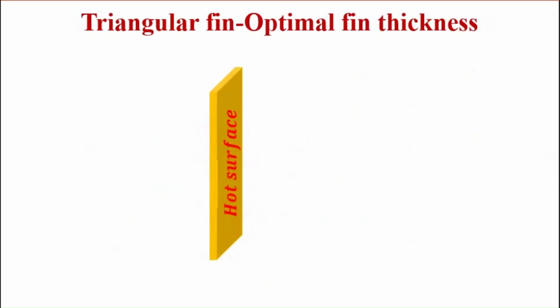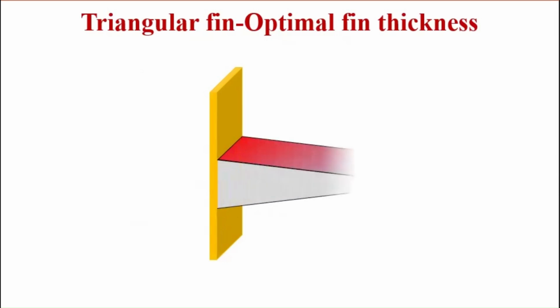Electronic surfaces don't have enough natural surface area to remove heat quickly. For this purpose, these systems are often equipped with extended surfaces called fins. These fins extend from the system body into the surrounding fluid to enhance heat transfer. Adding fins provides more contact with the cooling fluid. For this reason, the selection of fins is one of the most important steps in thermal management systems.